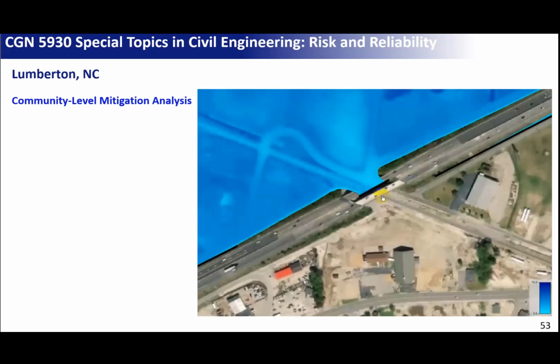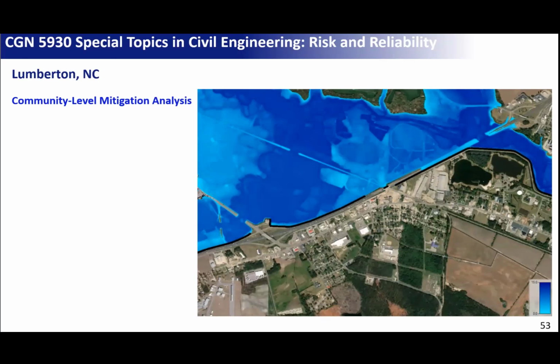And this is part of a longitudinal field study to validate not only the hazard, but also the damage. So we go collect high water marks, we go to buildings and measure the water level and compare it with the hazard model. And also assess the damage, like we do interviews with the household. How much losses do you have? How much insurance claims did you get? We also do visual damage assessment from the outside of the building and see how much damage they have. And we develop damage fragilities based on the damage that we see in the field, not the numerical models. And we keep comparing between them.